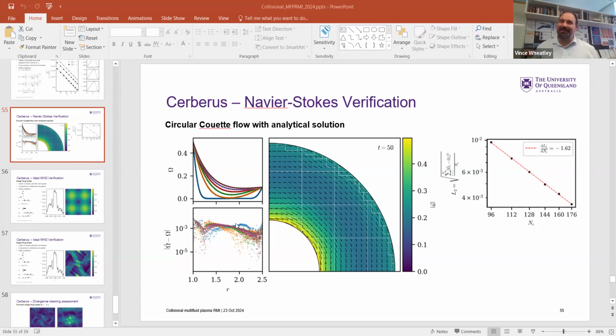Because we've slightly de-stiffened the problem, the electron density is usually 100 times lower than the ion density. It should really be 1800 times lower. But it is different from a multi-phase flow because we're modeling dilute gases. They can occupy the same space and time because we're using a continuum approximation of particles that can be intermixed. So it's not the same as a multi-phase simulation where we have discrete droplets, for example, surrounded by gas. Instead, the two gases are intermingled.